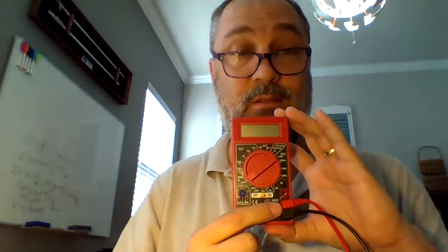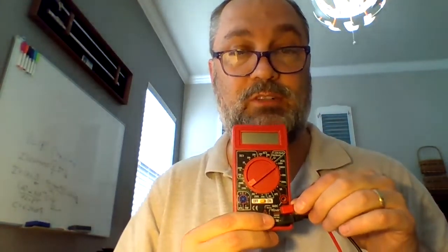Okay, so right here is the DC voltage, and here is the resistance. Right over here is where we plug in the leads. You'll notice I put the red one into the voltage and resistance jack, and the black one in the COM. If I wanted to measure amperage, I would remove this lead and stick it into the amperage jack. I never do that because I don't like blowing up my machines. As long as I use this for less than 250 volts, I'm good. So then I turn it on.